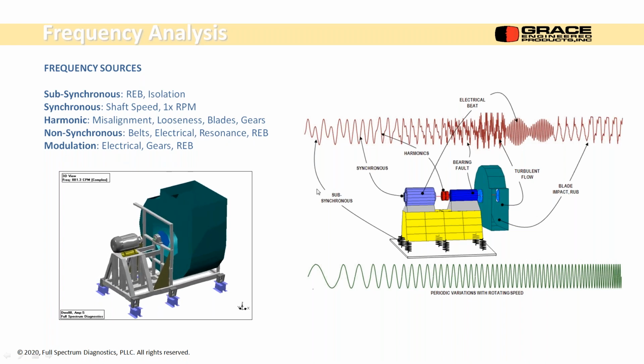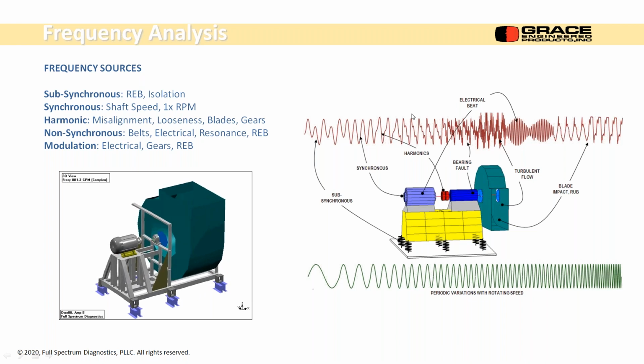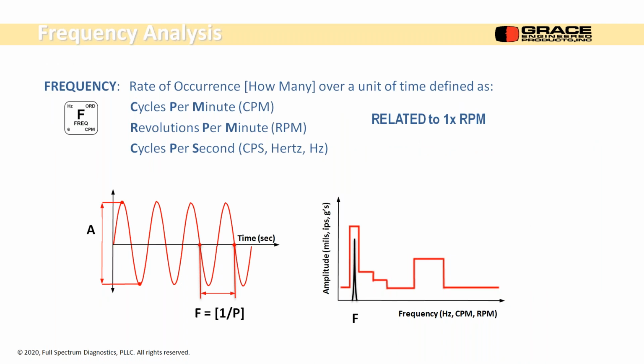If we're only looking at the time waveform, we're not seeing the frequency content. We're not seeing the individual peaks in the spectrum and seeing what percentage of each peak is adding to the problem. But we can calculate it. So the way to probably do this would be on demand, or at the beginning or end of a run cycle, capture a full spectrum and store it in the database. Otherwise, you can continue on with just the overall amplitudes.